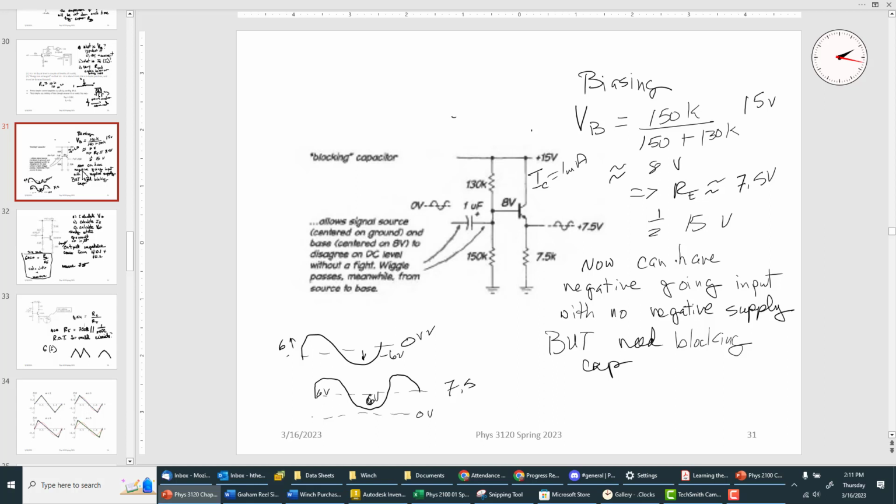So write it in your logbook, of course, so you see it, and then take note that now you don't have a negative power supply, but you can put a V in that goes negative. And you should explore what the limits are, like how much amplitude. And if you can't produce enough amplitude, you can always use the offset button to explore the limits.